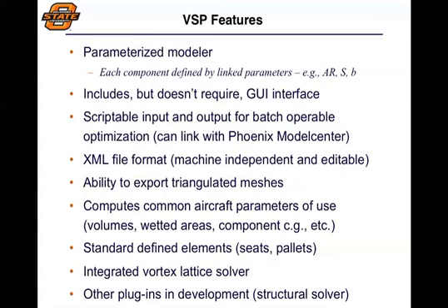Now, again, it does have a lot of other features. There are some standard defined elements that come with VSP, so you can start putting certain things in, like engines and propellers, and do that very, very quickly, like you couldn't do in a CAD program since you'd have to define those from scratch. Airfoil profiles are often pretty difficult to put into CAD programs. It's very difficult to draw an airfoil because it's got a unique leading edge, unique trailing edge.